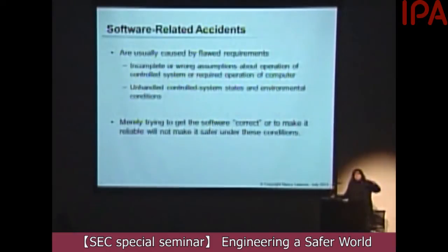For example, we lost an F-18 when it got into an attitude that the engineers had assumed was not possible for the aircraft. It was possible, the software didn't handle it, and the aircraft crashed. That wasn't a coding error, that was a system engineering error.